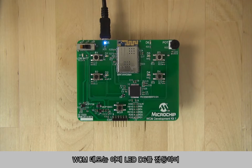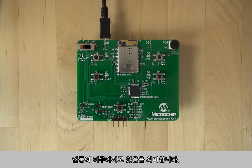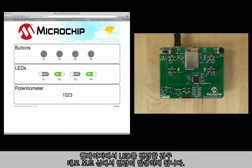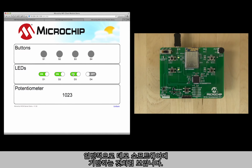The WCM demo will now light LED D6 and have a circular pattern on the LEDs. This indicates that it is in the process of associating to the router or AP that you have chosen. When it is done associating, it will connect to the server that you have entered your IP address for. When you change the LED on the web page, you will see that they change on the demo board. As this requires the board to poll the server for the change of status, there are normal latencies seen based on the software of the demo.